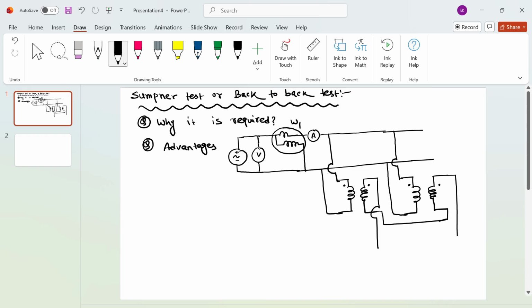Okay. So if I connect in series the non-dotted terminal, then what will happen? Let's see. Your supply is there. So your secondary side is open circuited, so some current will flow through the transformer. Now let's say these two transformers are identical. So transformer one is drawing exciting current of IE. Since both the transformers are the same, the other will also draw exciting current of IE, and the current that will come from here is 2IE, exciting current.